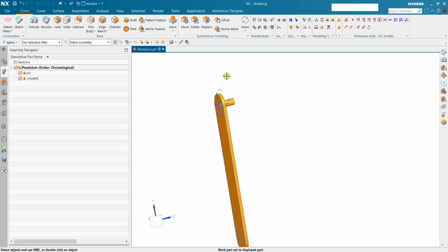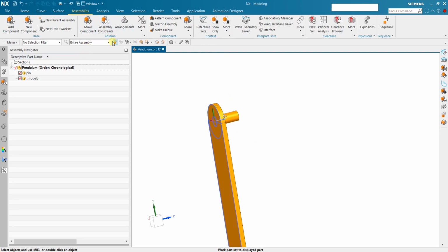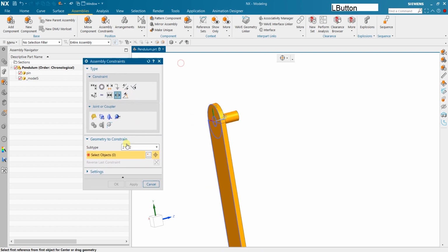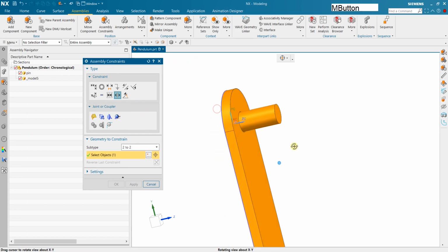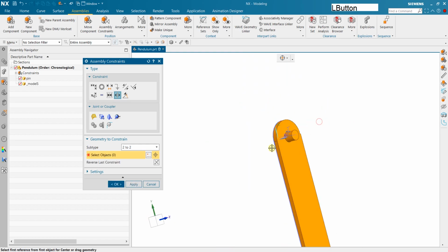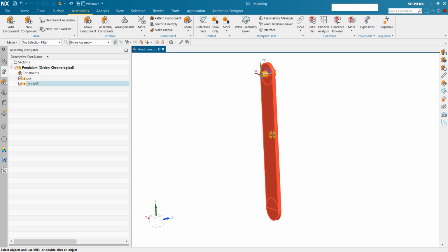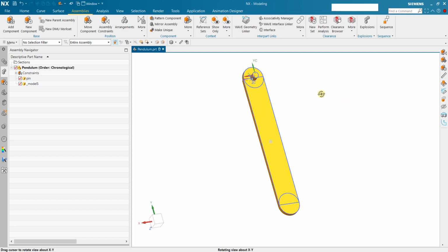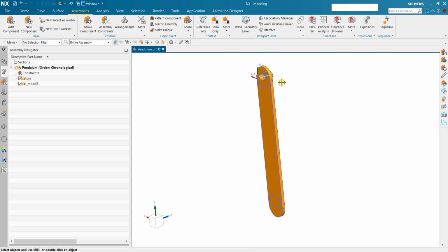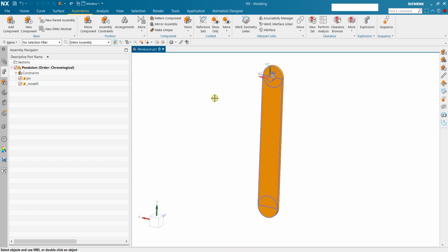There is no connection, but you can go to assemblies and assembly constraint to actually connect. For example, let me just center these two parts. You can basically go to the assembly constraint. Here, center 2 to 2 means you select two faces, this face and this face. They should be centered, like this. So all these assembly constraints will help you to move the objects to construct your initial condition when you move to the motion. So let's move to the motion. I think it's enough for now.